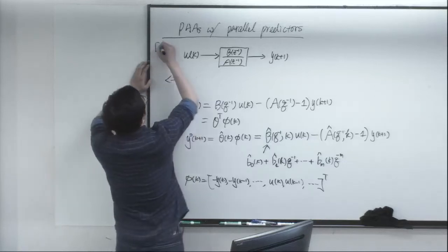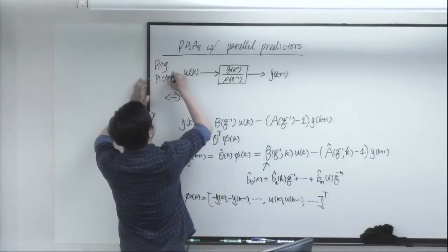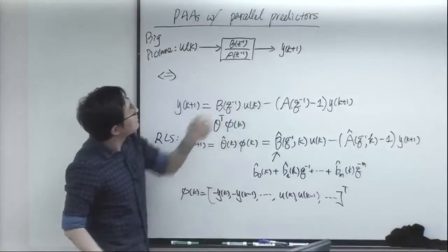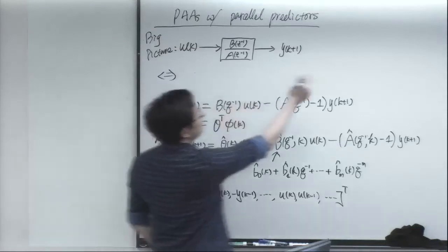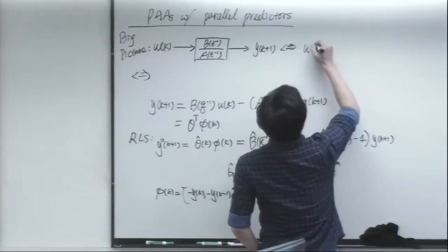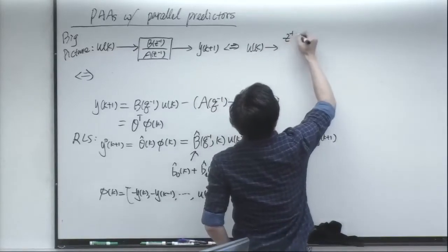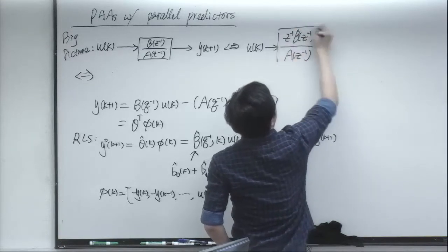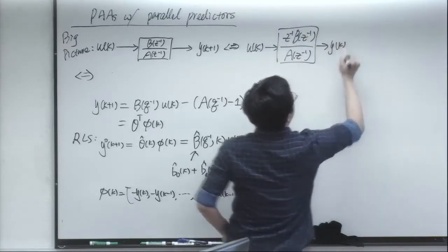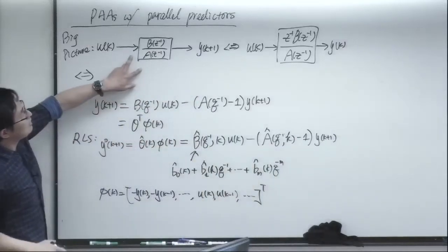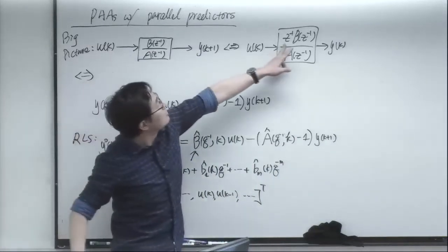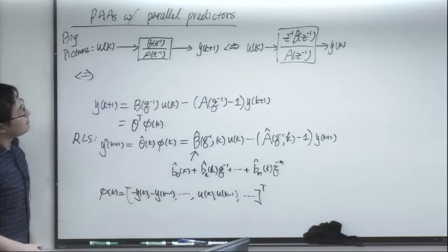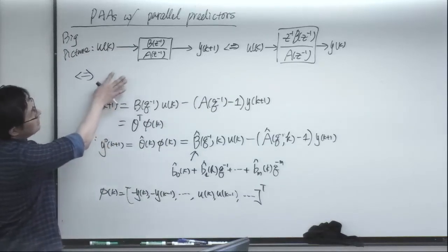So far, we have known if we have an input-output structure u_k to y_{k+1}, remember my notations, this is really saying that my plant has a one-step delay inside. And I'm just writing in this structure to eliminate this one-step delay and absorb it in this y_{k+1} fashion. So an intrinsic one-step delay is assumed here.